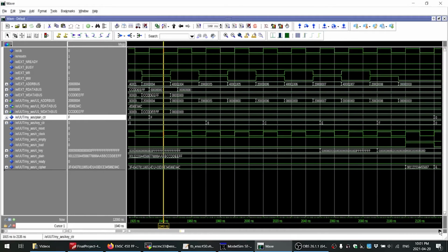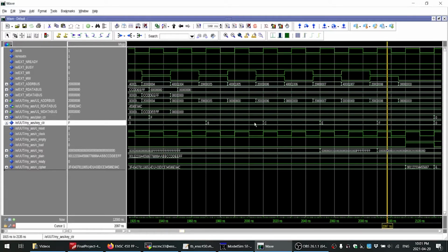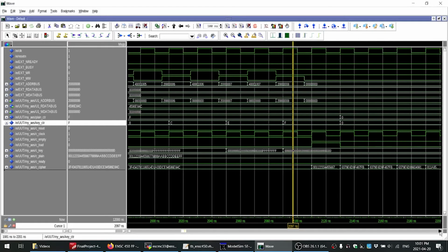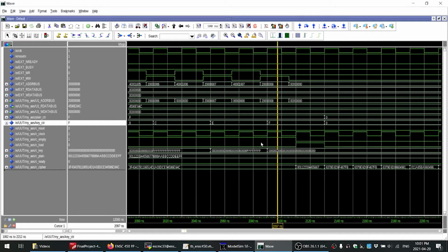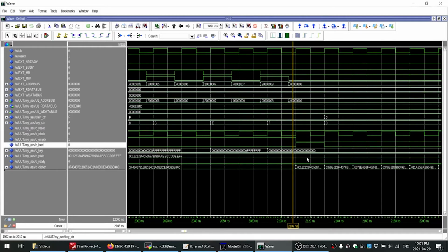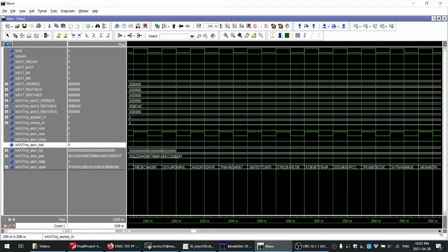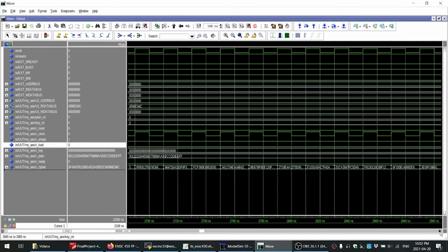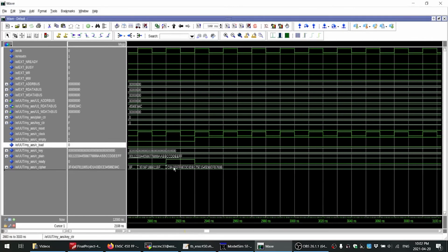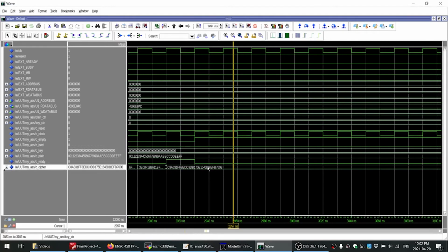And since the cipher text is all zeros in the SRAM, you can see it's all zeros, but it still gets received, and the counter for the key becomes all ones, and counts up to 16, and then it's ready, and the AES core starts computing, and it computes for about 600 nanoseconds again, and the output is ready to be read now.